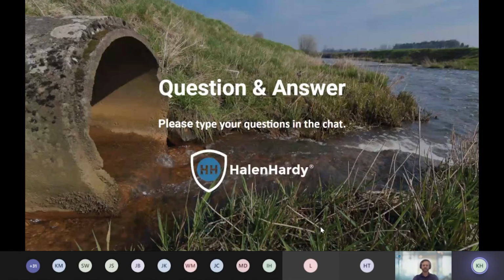Another one would be to, depending on what the process is and depending on what's blowing, look for any kind of a wet process that might be used. So if it's something that's creating a lot of dust, maybe from a tool or a machine, often those can be fit with some kind of a sprayer on them that helps to basically knock those particles down. Now it's going to create a sludge for you to deal with, but the sludge is a lot easier to deal with than particles that become airborne.